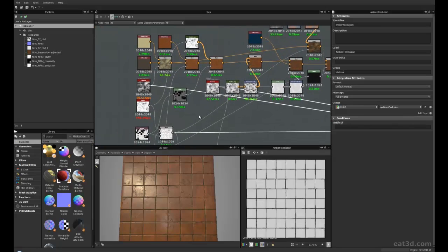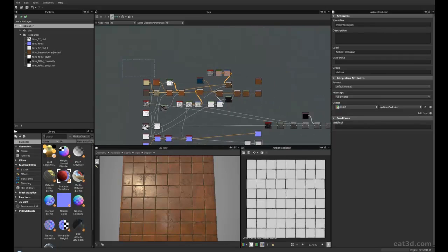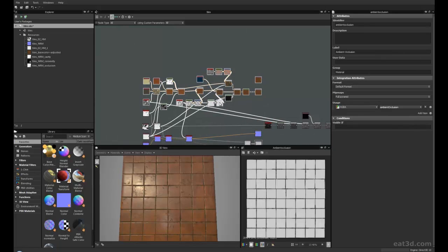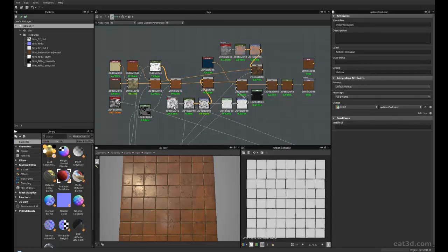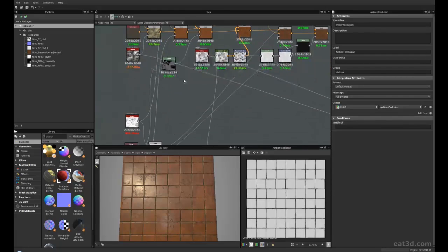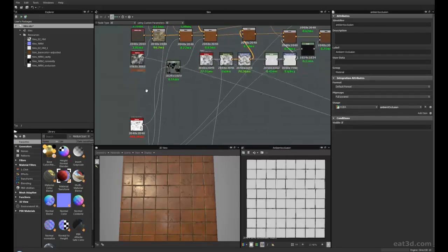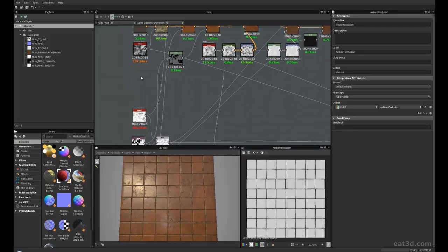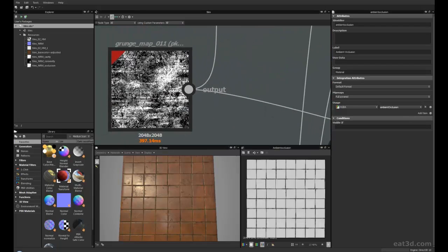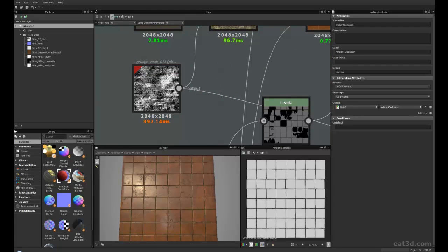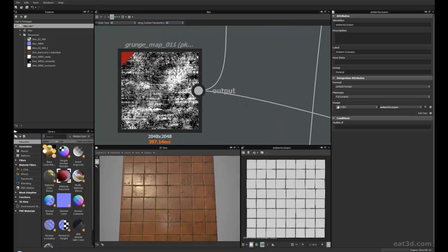So let's have a look at the actual albedo map. Let me just grab this, so we can differentiate what's happening. It might look intimidating, but it's not. It's pretty simple. All I'm doing is using these generators and masks and making my own FX maps, creating all these different masks, because they're not height maps anymore. Don't think of these as height maps. Think of these as masks. Where it's white, you're going to see it, and where it's black, you're not going to see it.